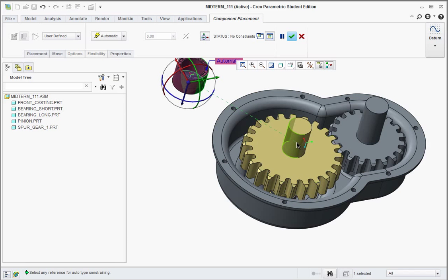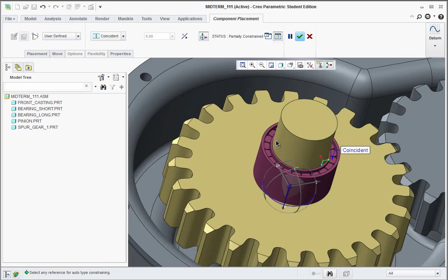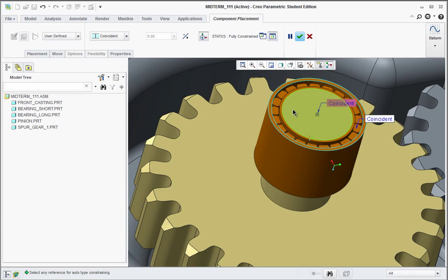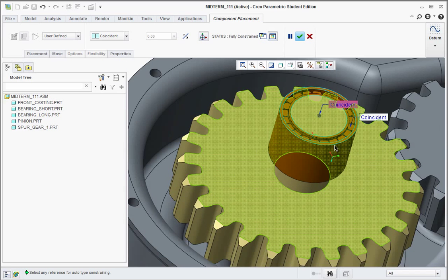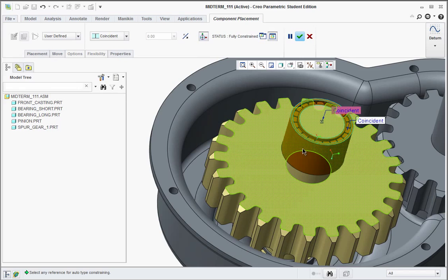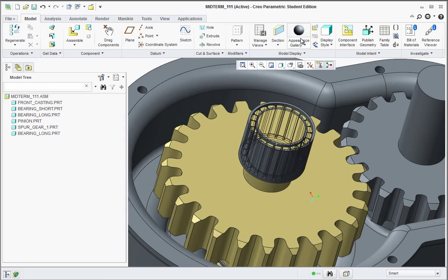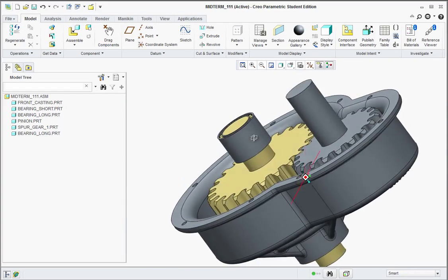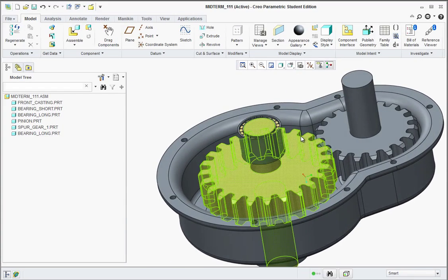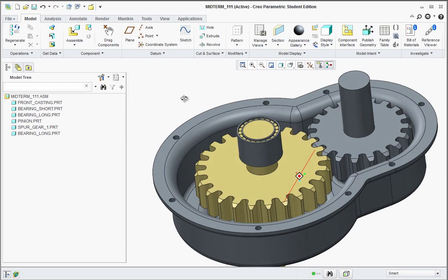The cylindrical face to this cylindrical face, and then the end face here to the end face. Now once you model the other part, there's actually a slight, actually a very significant interference between this end face and the other part you model, but don't worry about that right now. I usually give that as an extra credit project to fix, so for 10 points extra credit,